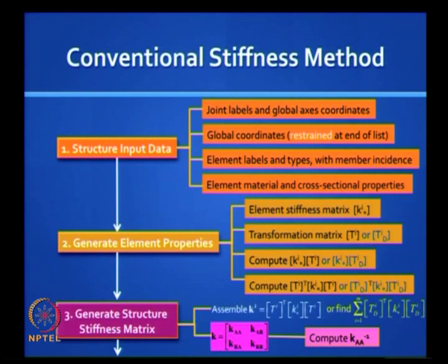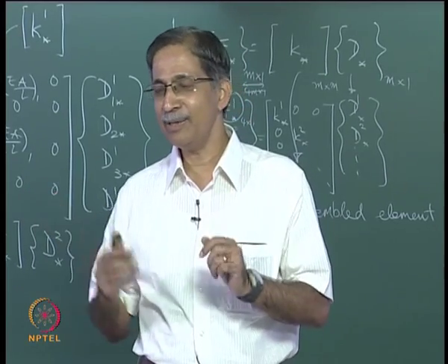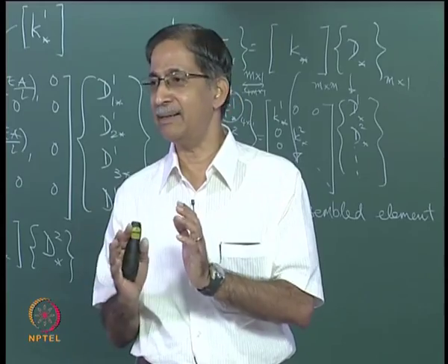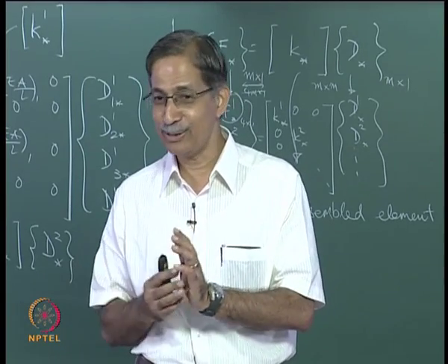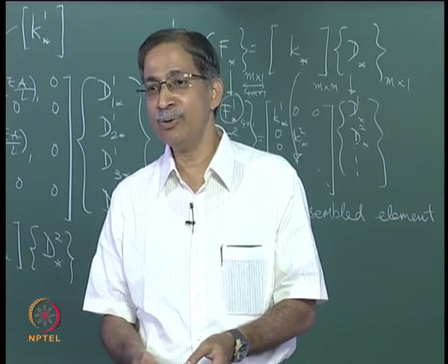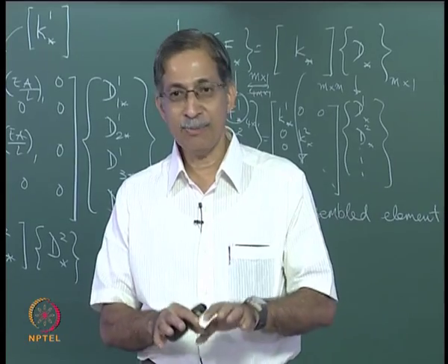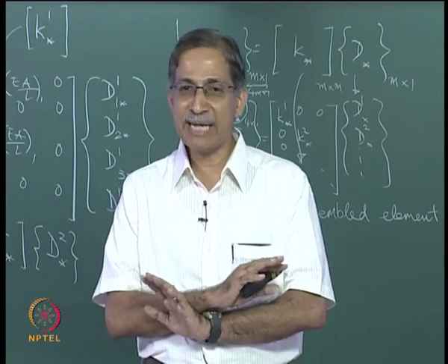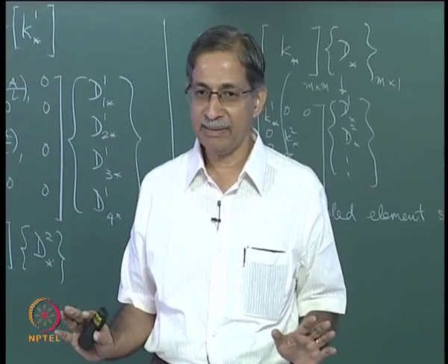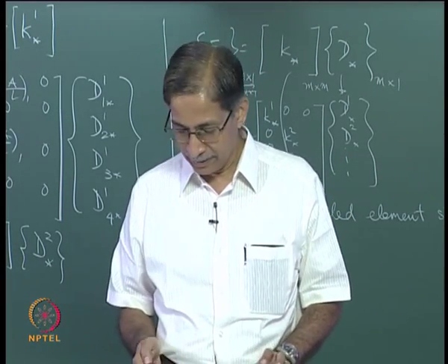So you do not have to invert the whole K matrix. For example, the truss problem, only K1, only 1 and 2, those coordinates. So K is really small, and when you learn in the university, they teach only that, Ka. So you do not see Kr, you do not see Kra, you do not see Krr, so you do not get confused. Now you get confused, but then you are trying to see the big picture and trying to see what is really going on. You are trying to capture the complete displacement field, the complete force field, and you decide what you want to do.